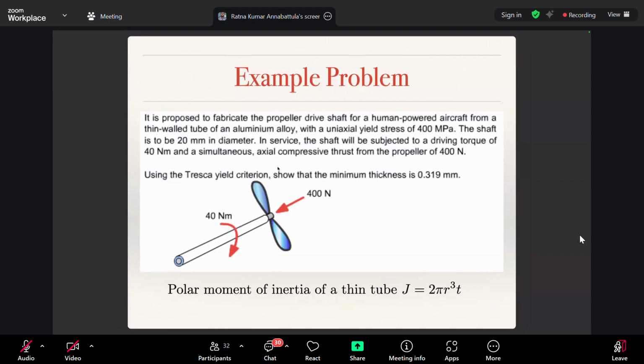Even in the three-dimensional case, the maximum shear stress is what matters for shear yield strength, and in the case of distortion energy, the equivalent stress is what matters. Okay, sir. So you need to find the principal stresses sigma 1, sigma 2, sigma 3, and the difference of the maximum and minimum principal stress, divided by 2, will be the maximum shear stress. Fine, noted, sir. Thank you.